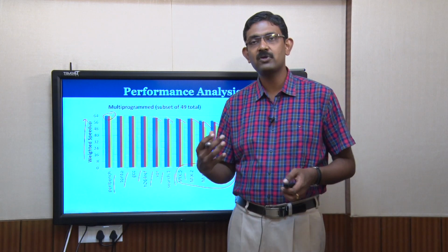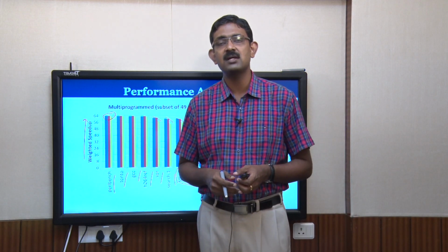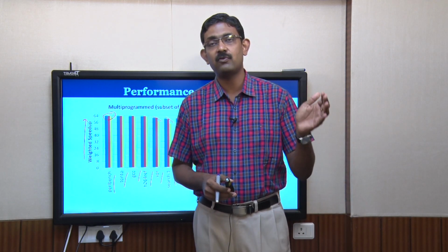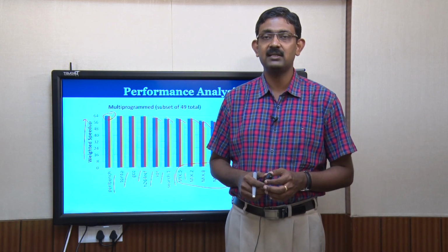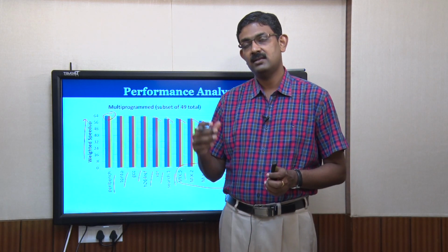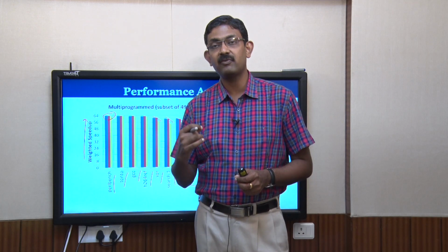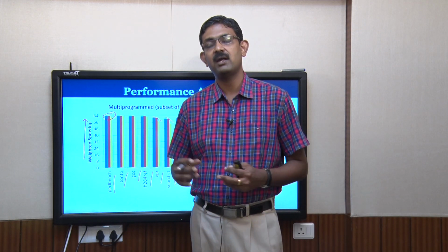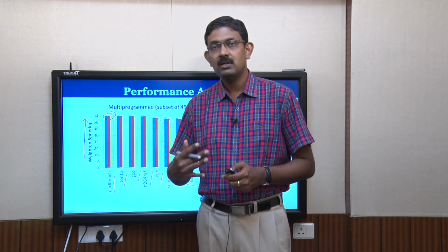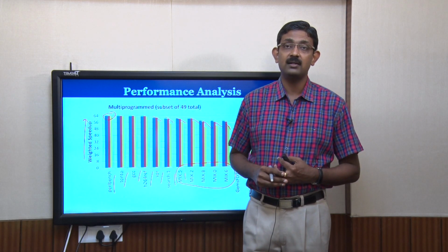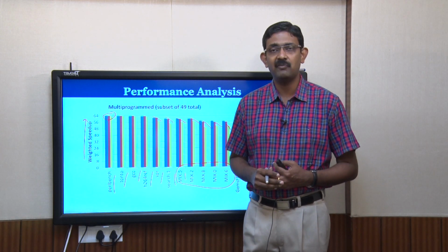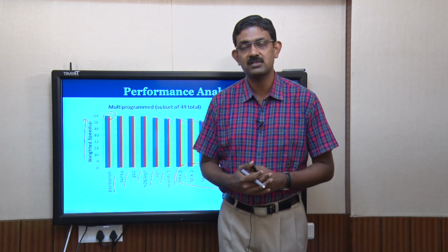We have seen two types of deflection routers today. The first one is completely bufferless, and we have a total ordering sorting circuit followed by a sequential port allocation, that is called the BLUS router. And then in the second one, this total ordering is replaced with a Flit called the golden Flit, followed by a parallel sorting circuit, that is called the permutation deflection network. So, these are the two standard bufferless deflection routers that were proposed half a decade ago. Still, it is a very active research domain.